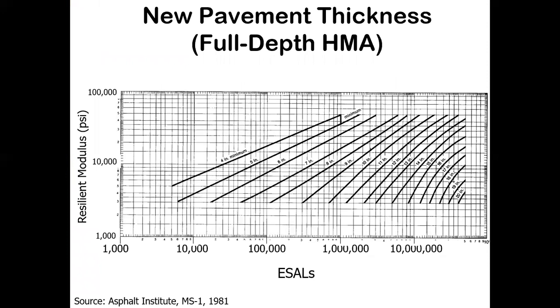Now, once you know the resilient modulus, you draw a graph: make a perpendicular from 12,000 on the subgrade axis, and you know there are 3 million ESALs, 30 million ESALs. When you draw the graph and find this intersection, the estimated thickness is around 14.5 inches.